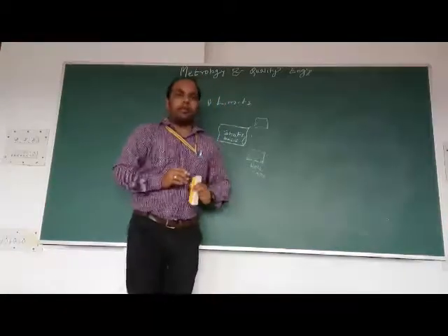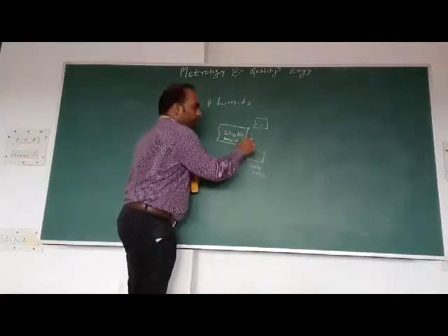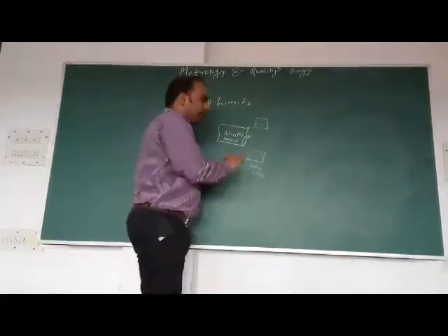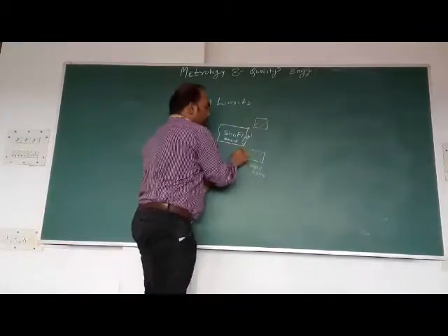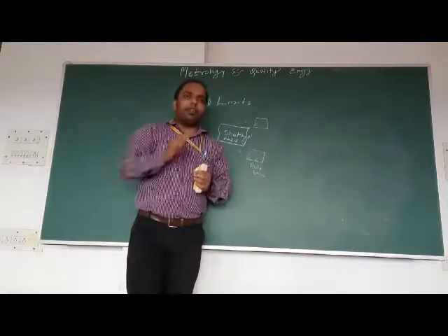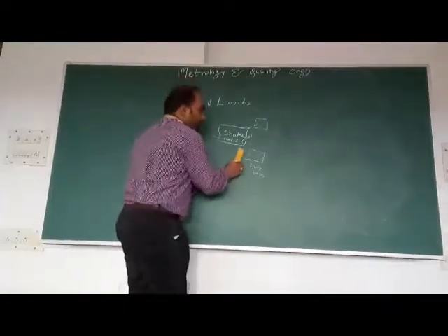Now as you can see, when we talk about assembly, either the shaft goes inside the hole, whereas in some assemblies the hole is being fitted onto the shaft. Dependent on these terminologies, shaft basis and hole basis, two systems have evolved.